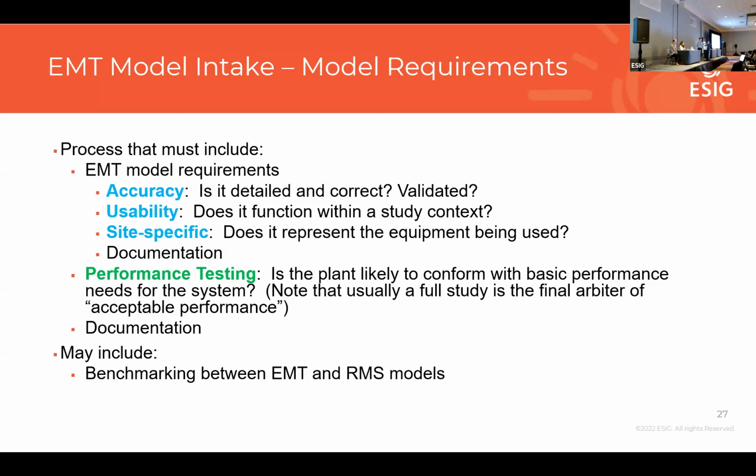And then taking accuracy to the next level: is the model validated? This is something that's done in a few regions. In ERCOT, for example, they ask for a unit-level model validation report. This is essentially checking the model against the performance of the actual equipment, in one way or another. Typically, this is a hardware-in-the-loop type test, where you can validate those controls against actual equipment. That's awesome if you can get that for accuracy. We don't always get that, but it's really great to have.